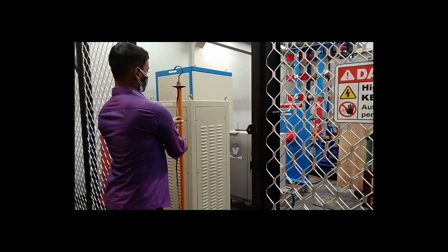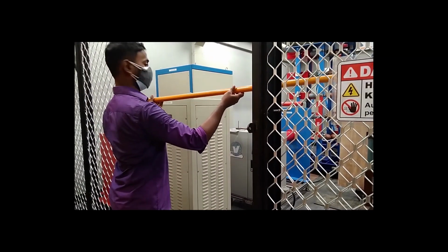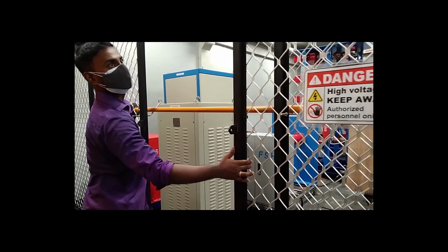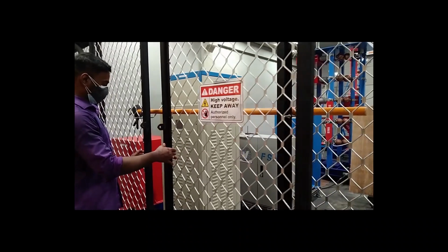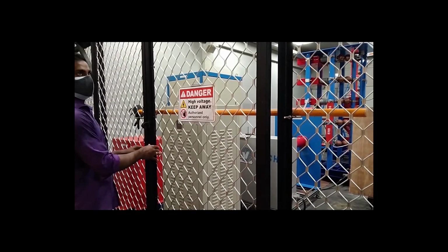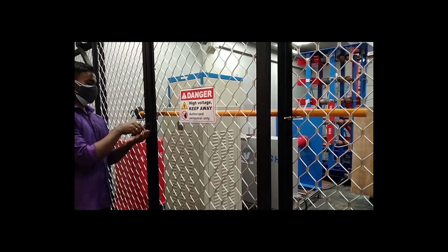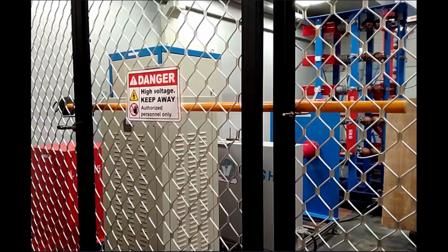After arranging the wire mesh with the conductor, you have to close the door of the lab setup as shown here. This is done as a safety precaution. If the door is not closed properly, you can't turn on the breakers to operate high voltage sources, so that it ensures the safety of people.